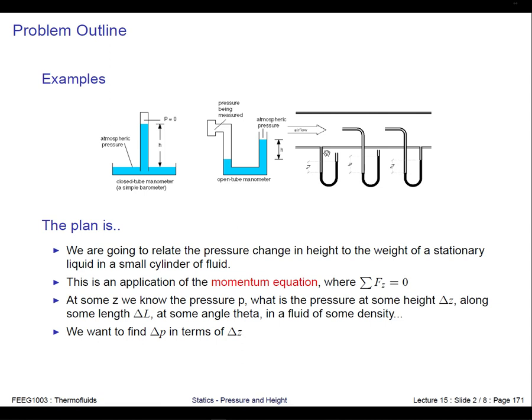In the first U-tube manometer, one leg is open to atmospheric pressure out here, where there's no fluid motion. The other leg is in a flow, going past this gap, so the pressure at this point is different to the pressure at that point, and we measure this height. With a few calculations that we'll come across next term, we can work out the fluid velocity based on this height difference.